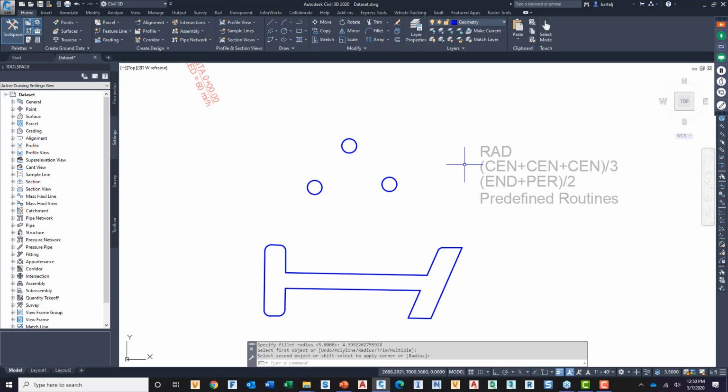All right, so it's not just single picks. We can also do some math. We looked at geometric center before. I've got 3 points here. Maybe they're borings or something. I'd like to find a point that's in the geometric center of these. Can't use that command for that because it's a point that's in space and I don't have an object. But what I can use is the object snaps to determine that.